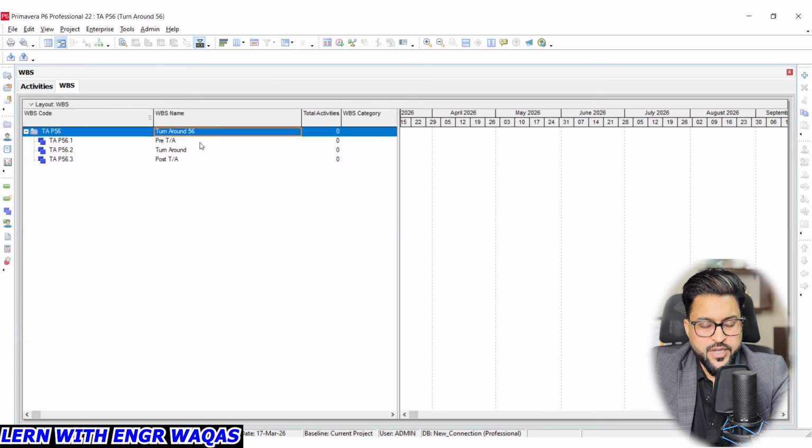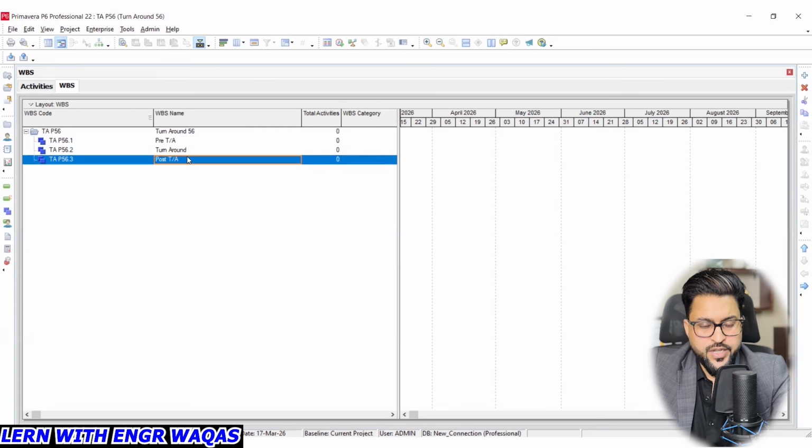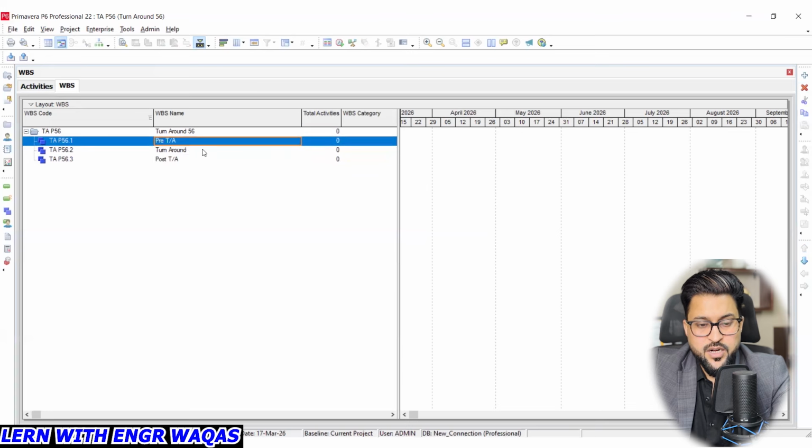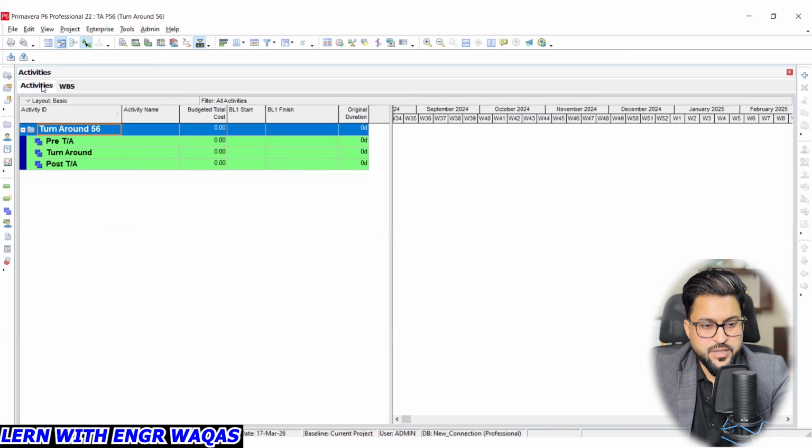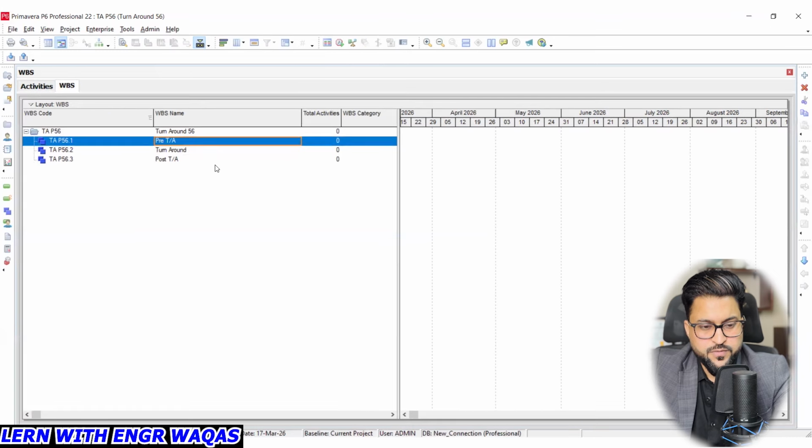Okay, so as soon as you are going to create three major headings, you have divided your complete turnaround package. You can write here your plant name, you can write here your shutdown or turnaround number. And as soon as you are going to create it, this is called this higher level WBS or control account, right? And I will switch into the activities, and I can find that created WBS will be represented in this way over here, right? So that is the first thing, you understand. So this is actually activities window. This is your WBS window. Within WBS window, you are going to create your project higher level information, that what you are going to do. You are going to divide your project into different kind of categories one by one.